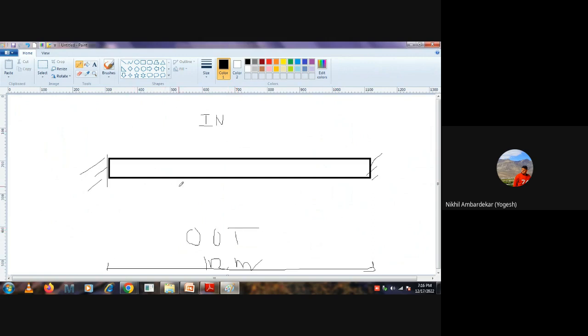Because of the wall pressure and because of the fixity, there will be positive bending moment. At these ends, this is negative, negative, this is positive. So ideally, same thing, you have to provide reinforcement for negative, like this is the hogging, no? So you have to provide it somewhere here, here, and for the positive here. Same thing happened, reversal of the loading because of the soil pressure.